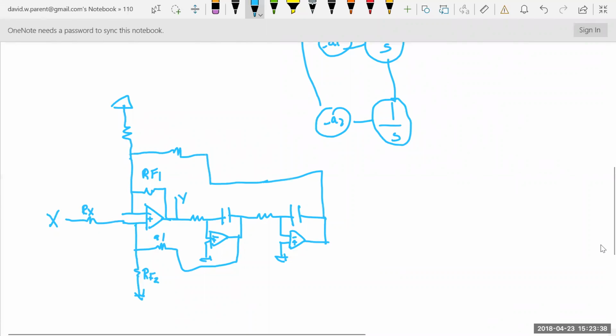And see how if I draw it like that, you might make fewer mistakes. Now at this point, you can put a dummy, because depending on the values of R and C, you can get away with not having a dummy. You can do this, you can do that, or that is the dummy, actually. But I found it easier just to put 2 resistors of the same value because the gains didn't add up.